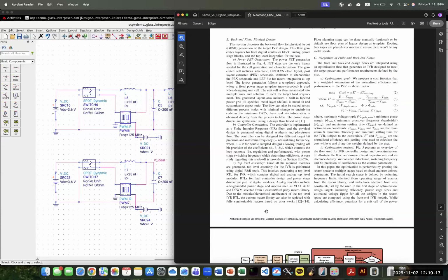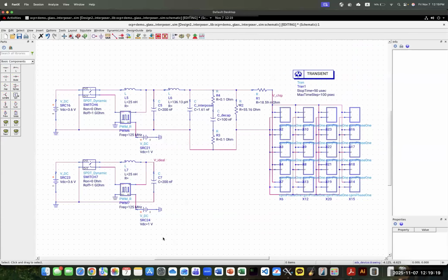As Sigmund mentioned, he picked up the IVR. Typically, it's high switching frequency. Next we'll look at refining the package PDN or the RLGC model of the package. Probably do a first level power insertion and see what the values are.